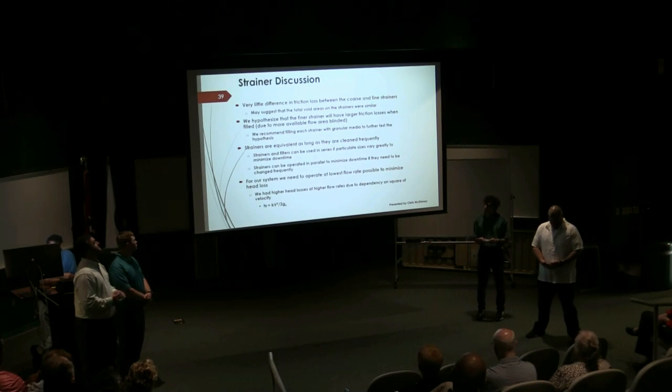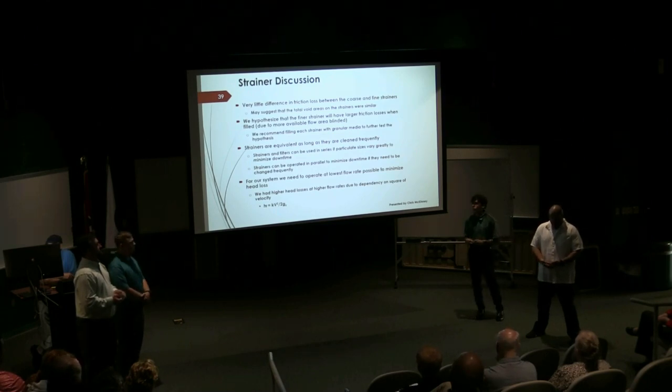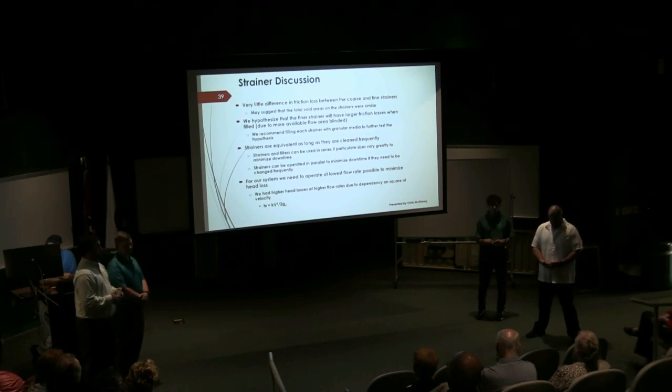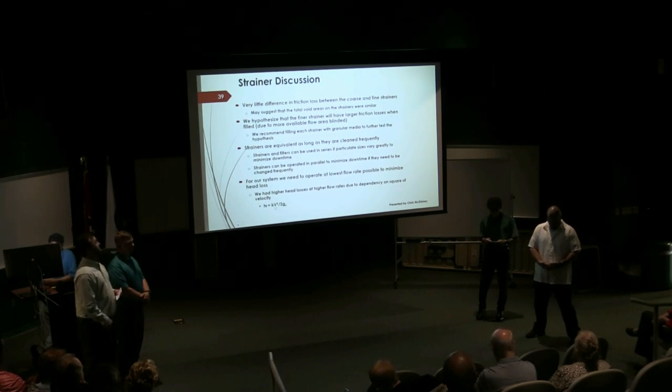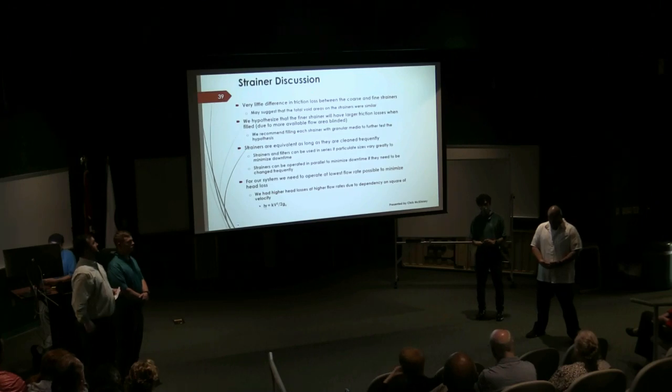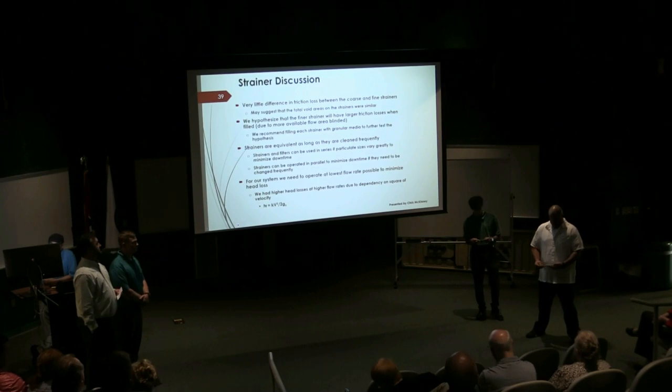Finally, for our system, we need to operate at the lowest flow rate to minimize head loss. We observe higher head loss at higher flow rates. This is mostly due to the dependency of the friction loss on the square of the velocity, versus the K value having less of an effect.